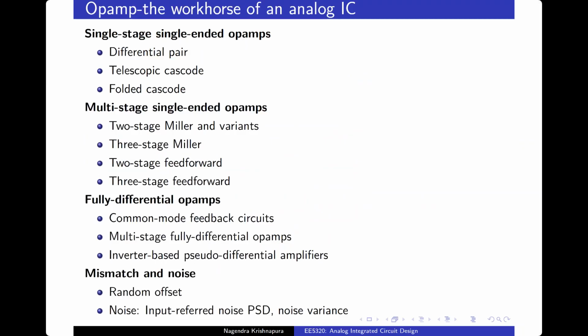Again, principle-wise, common mode feedback or any other feedback, it's the same. In fact, we saw that most of the equivalents of common mode feedback turn out to be either one or two stage op-amp equivalents, right? And of course, now these are something specific to IC that you have to calculate the effects of mismatch and noise. Noise was likely unfamiliar. So they all can be calculated in the same way, mismatch and noise.